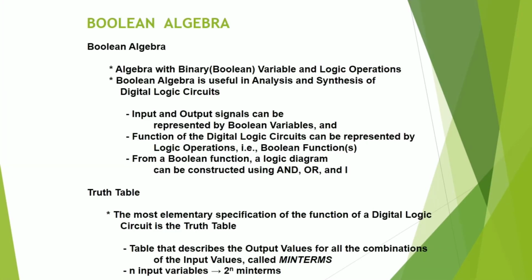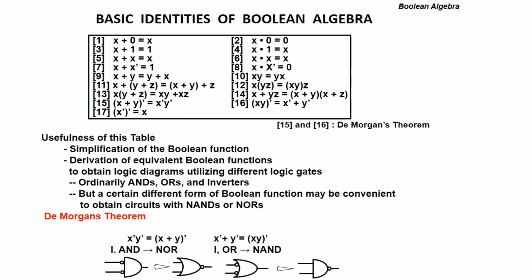Now we'll go on in digital electronics. What is Boolean algebra? Boolean algebra is nothing but some terms and conditions in which basically the AND gate, OR gate and the NOT gate terminology is used. Here is the tabular representation of Boolean algebra. Here let us see. X is the variable. You can assume any variable, say A or something else. Here we consider the variable X.